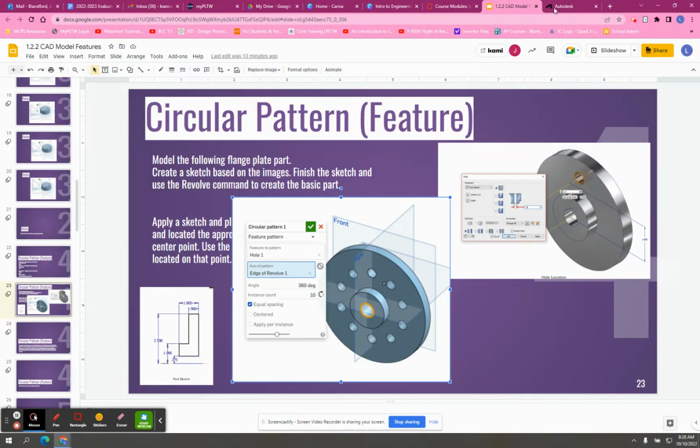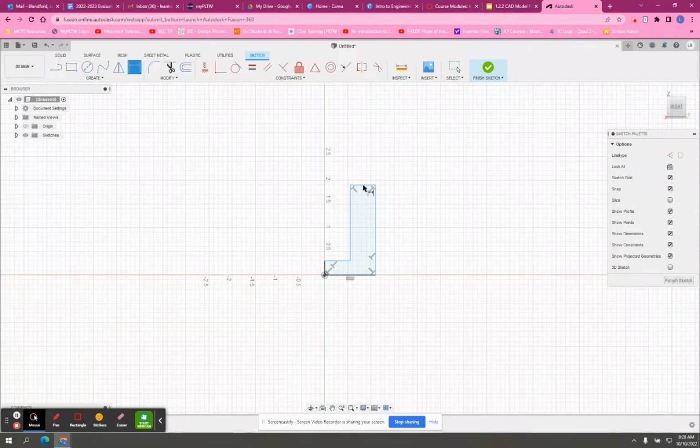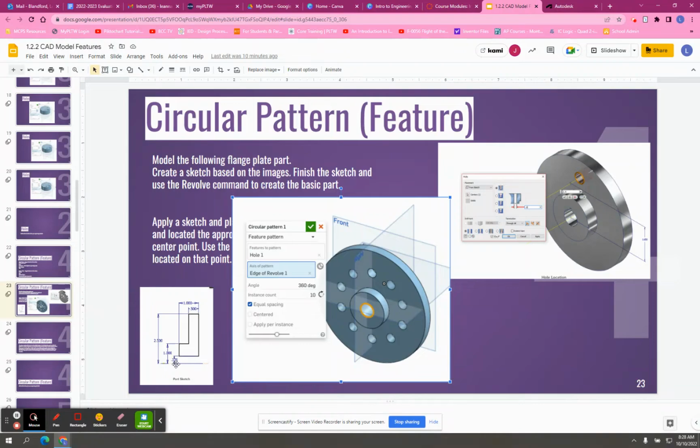We've got 0.5 and 1. Okay, so we're just going to go here, choose 0.5. And then distance from here to here is 1. Okay. Now these other dimensions are a little bit tricky. We have to do some math because this 0.375 throws things off a bit.